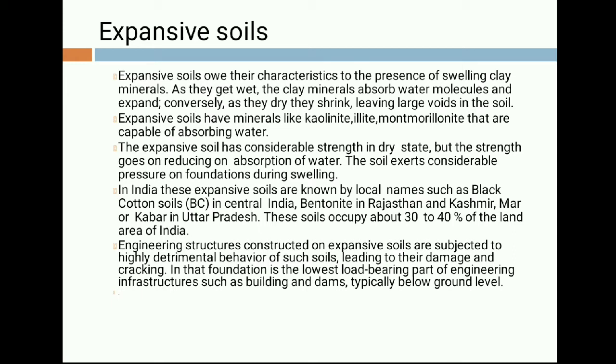Expansive soil have minerals like kaolinite, illite, montmorillonite that are capable of absorbing water. Means these are the minerals which can absorb the water in case of clay soil or any kind of expansive soil. The expansive soil has considerable strength in dry state, but the strength goes on reducing on absorption of water. The soil exerts considerable pressure on foundation during swelling.